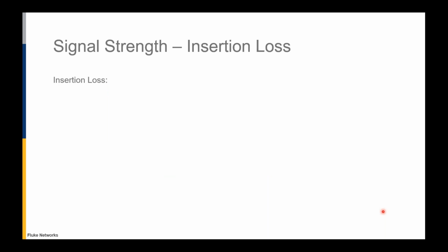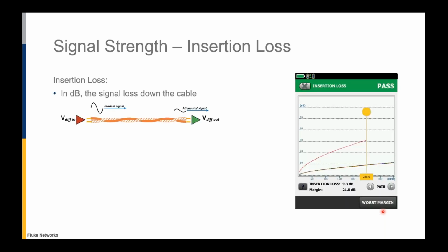Now, let's take a brief look. And again, I want to spend more time on our measurements of immunity, if you will, to EMI. But to understand that, got to start with the basics. The first thing we're going to measure is the strength of the signal that we're transmitting. Actually, the loss of signal, but consider it the strength. So we're going to send a given signal down a wire. It starts with a given amplitude, and at the far end, a lower amplitude of the signal.